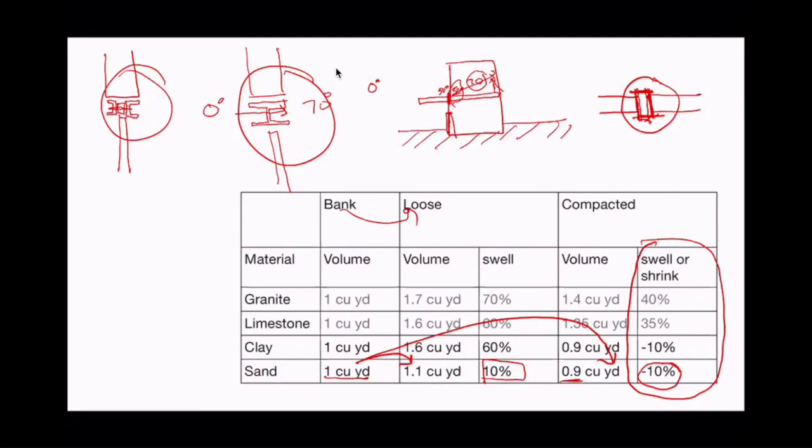Now, sorry, yeah, but your connectors are metal as well, so they're actually rigid. Sure, but it's all about the area of those connectors relative to if they were going all the way through. So that's what I was getting at. The goal isn't to have zero thermal bridges. The goal is to reduce the thermal bridges, in this case by 99%.